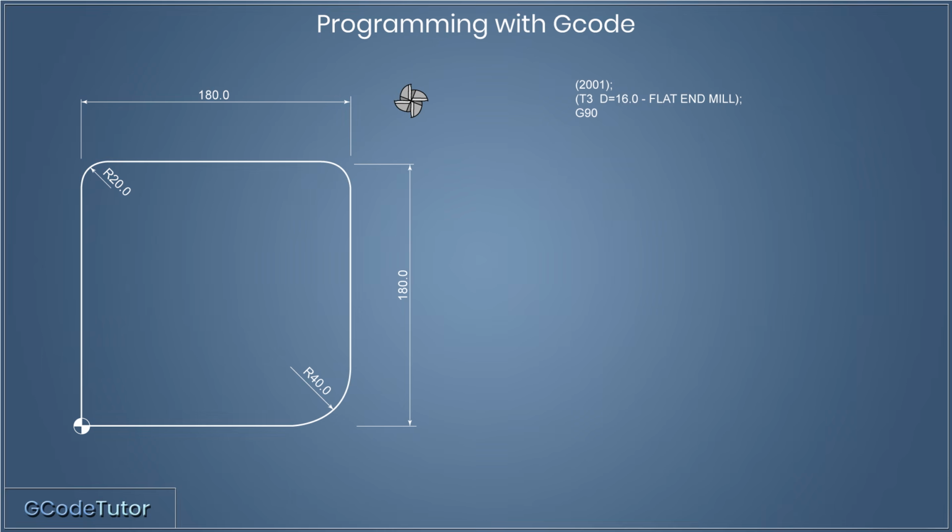So the first thing we tell the machine is G90. This means that we're using the absolute position system. So all dimensions come from our datum position. No matter where the cutter is or where we're going to tell it to go to, all dimensions run from our datum. So x0, y0 on the bottom left hand corner is our datum. So all the dimensions run from this.